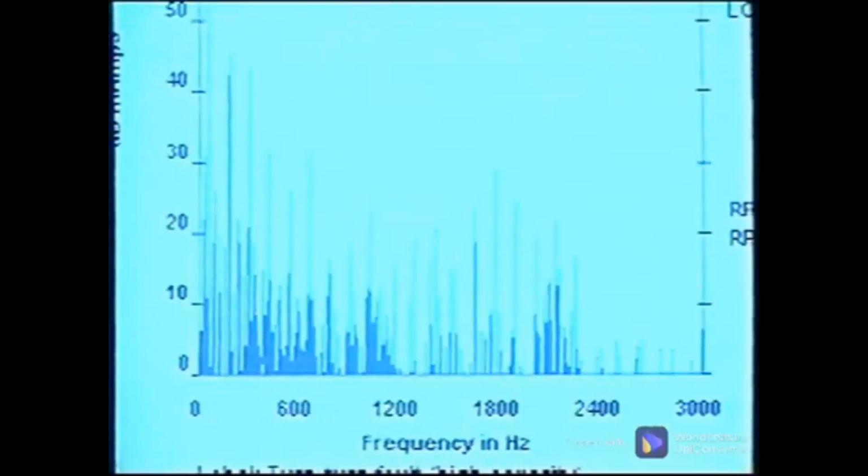Stator anomalies also show up in the frequency range surrounding the principal slot pass frequency. Sidebands are spaced at 2 times line frequency. Present research indicates that a significant amplitude increase in these sidebands correlates to degradation occurring in the stator.